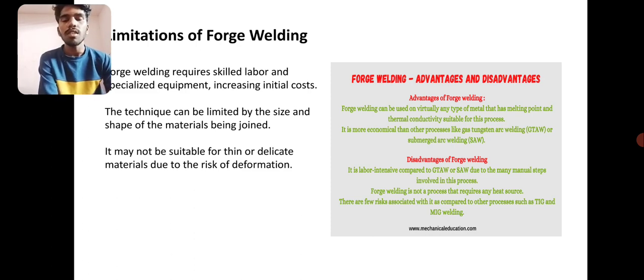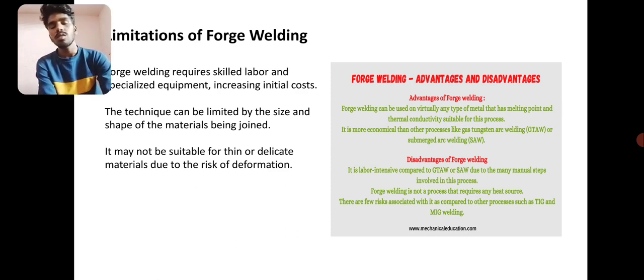Where there are advantages, there are also some disadvantages. It is not suitable for thin, delicate materials due to the risk of deformation. It also requires skilled labor, so any normal labor can't operate it. You have to know how to do the welding, so skilled labor is required. This is also one of the disadvantages. Especially, the equipment increases the initial costs. Any equipment we use for welding will be high cost. That's why these are limitations.